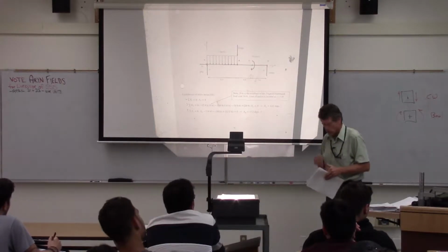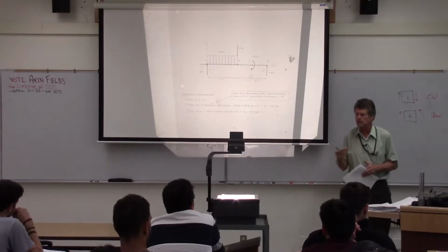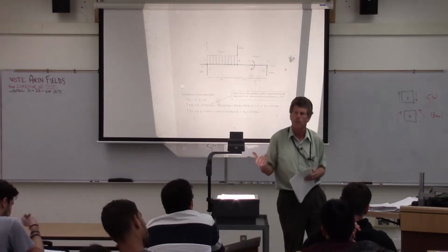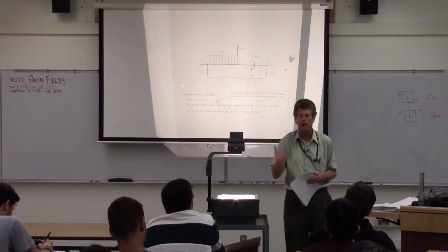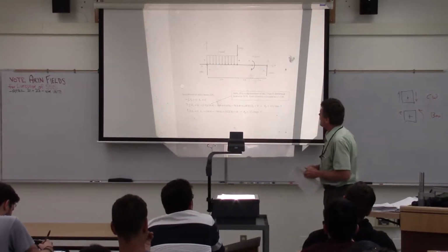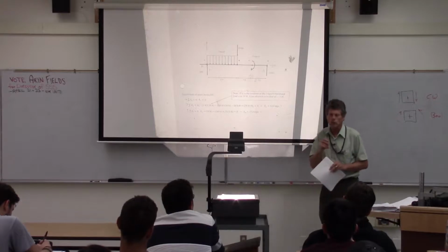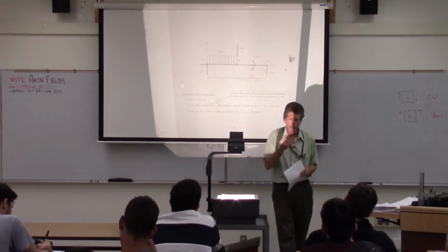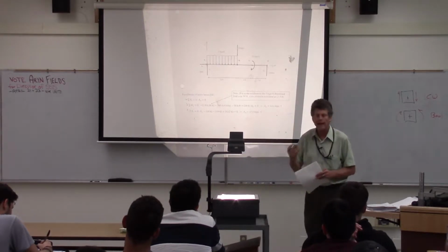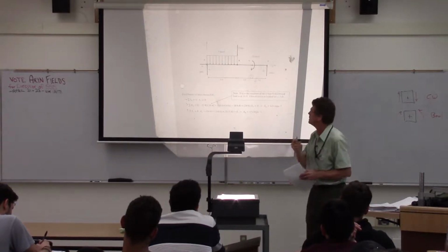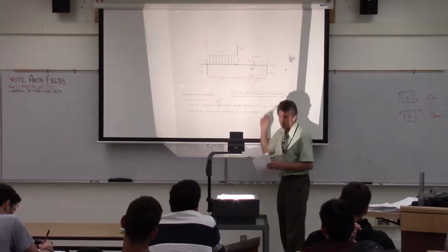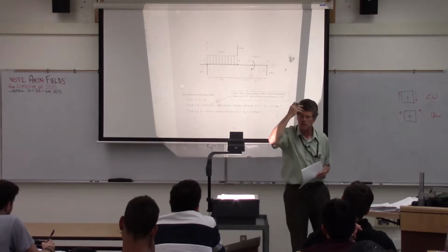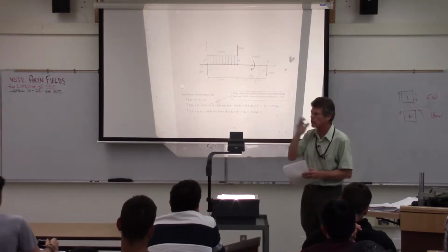Now, a couple of things. What we're doing now is we're going to do this method of sections, or the other way it's known as the equilibrium method, because what we're going to be doing is a bunch of free body diagrams and equilibrium problems. And we need to think about where we're going to be doing those. When we look at our beam here, the best way to look at a problem like this is in terms of the free body diagram, because notice this isn't a roller, this is a force. This isn't a pin, this is a force. You need to think about things in terms of forces and couples when you go across there.